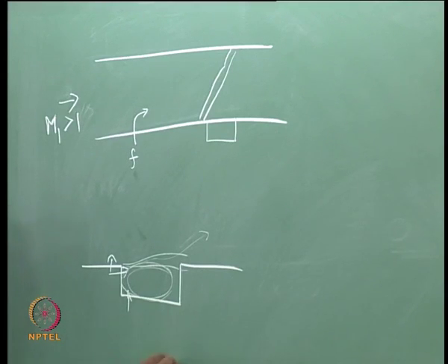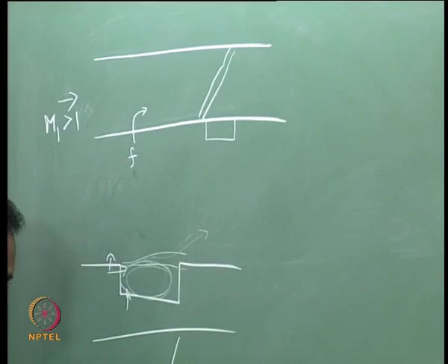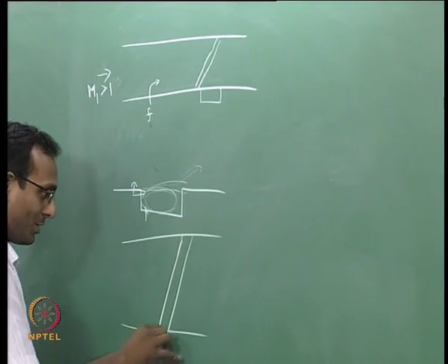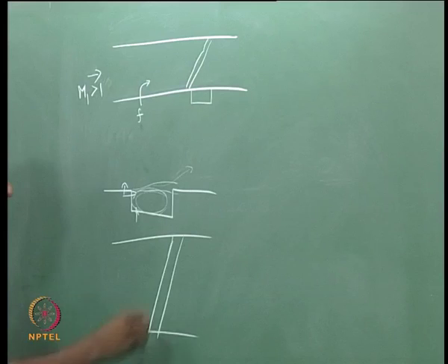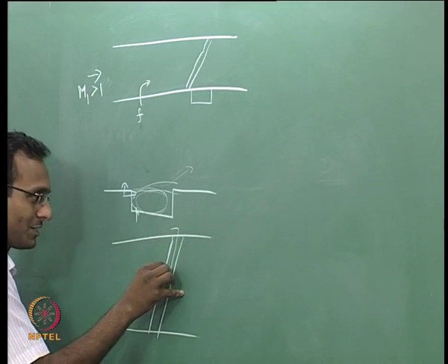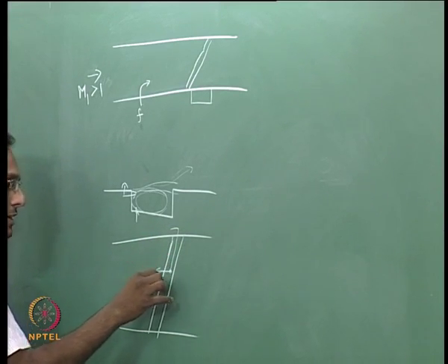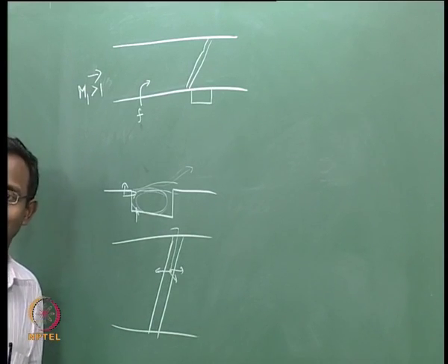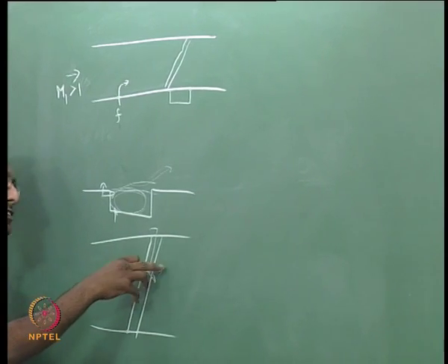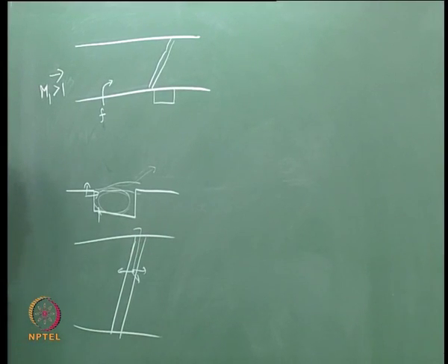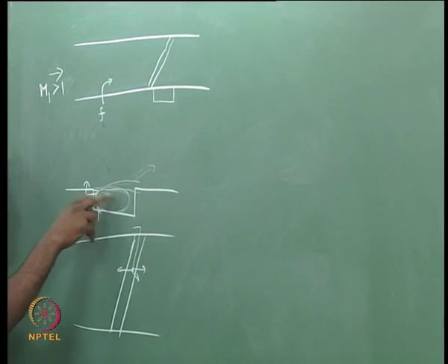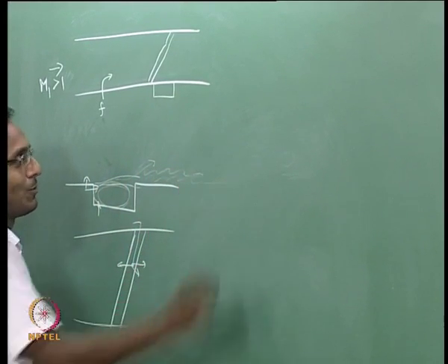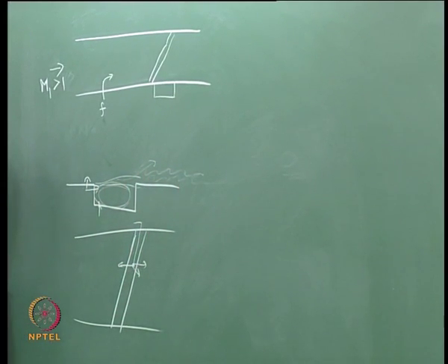Or I can have a configuration where there is a strut, which is just a metal rod sitting inside the duct, and I send fuel through this, and some holes in here will inject fuel this way or in the side or outward, anywhere, somewhere along the direction. Somewhere it will inject from inside here, and now we think about how to mix this better along with the flow. People think about this one more than this one because in this one typically the fuel will stay only along the walls, which will heat the walls more, because when the combustion happens, heating happens mainly near the wall.